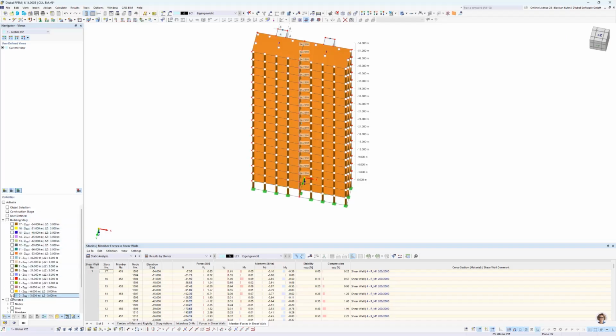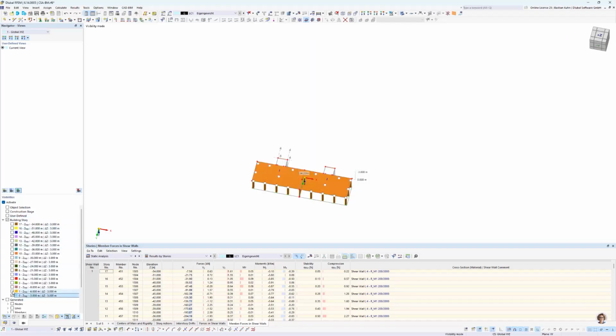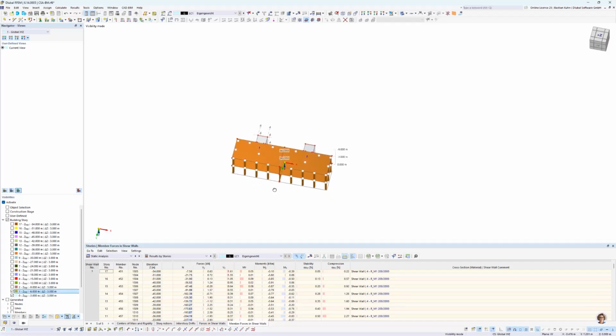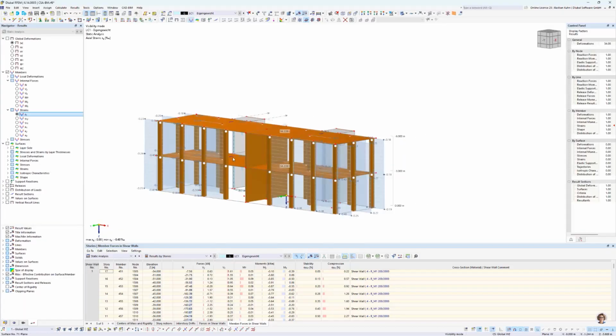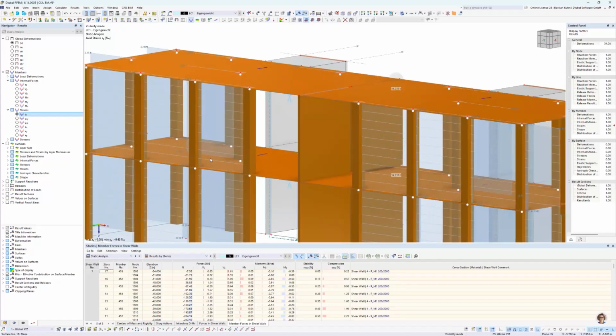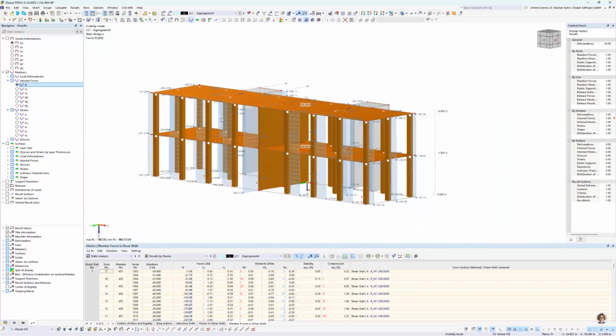In here, just display the first and the second. So the first one is assembled, then the structure is settling at least a little bit. There's also a strain on it, so maybe we bring the display results in here. So you see we have the strain on it, but that is the complete strain of the whole structure, so the force in the top story is moving away from it. So the strain is wrong, and also the normal force caused by this is wrong. And that is an effect that's occurring in higher buildings.